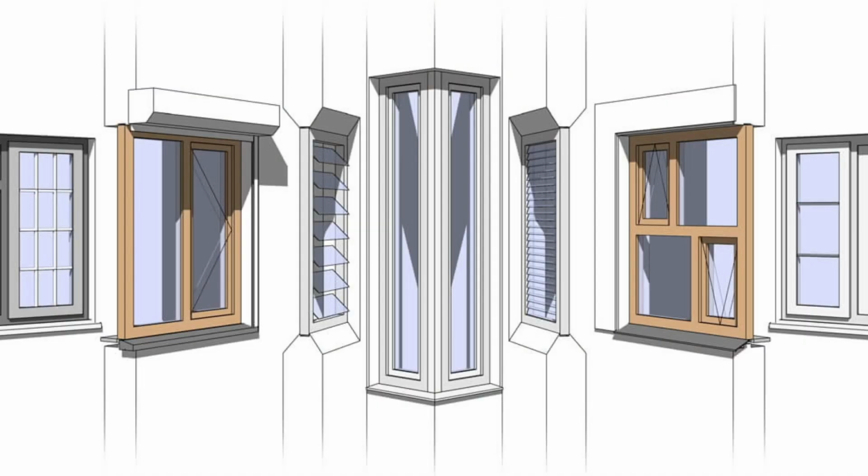Tip number 7, use adaptive families. If you're consistently resizing built-ins, counters, or furniture manually, there is a better way. One mistake is using static families for dynamic layouts. Use adaptive families. They adjust based on their placement and save a ton of tweaking time.